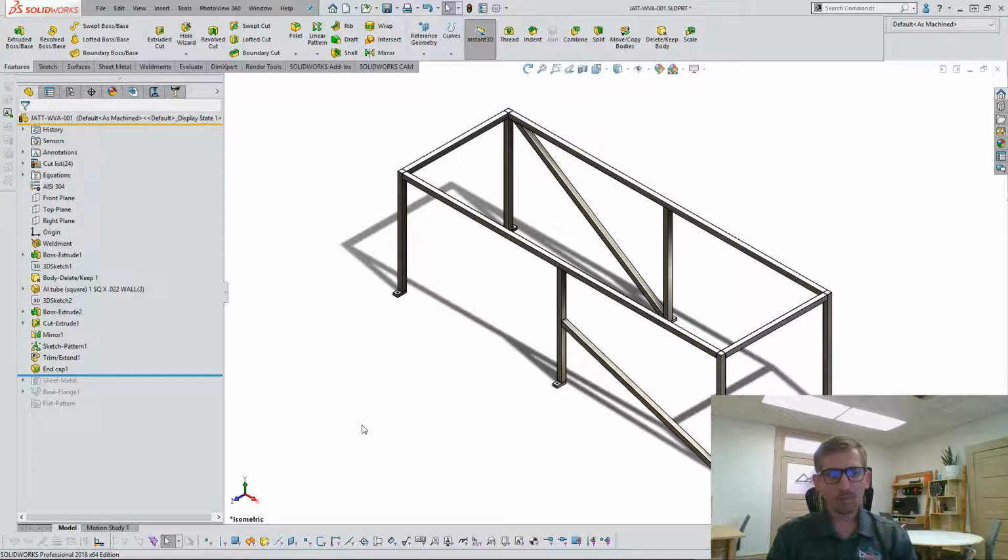The other aspect that I look at is when you are done with your weldment, such as this one right here, how is this going to look to your assembly team? Are they going to be seeing each individual leg and foot on there, or are they going to see this as one complete structure? Well, they're going to see it as one complete structure. So when deciding between weldments or an assembly, you think of, okay, what are these parts going to look like in the lifespan that they have on my shop floor? Part files and weldments and so forth are meant for your machine shop.